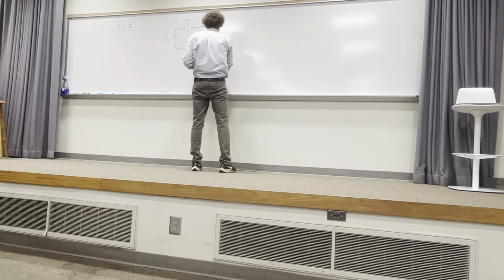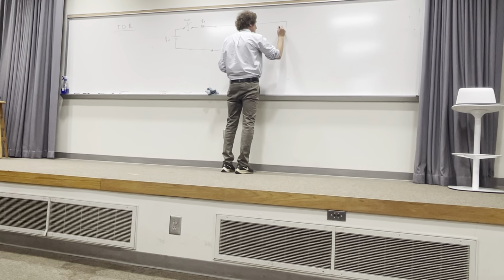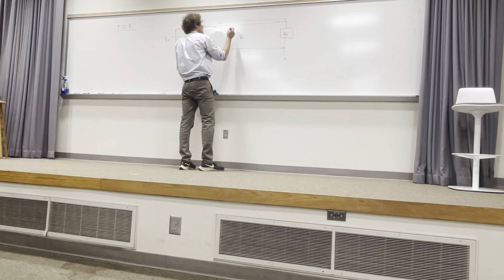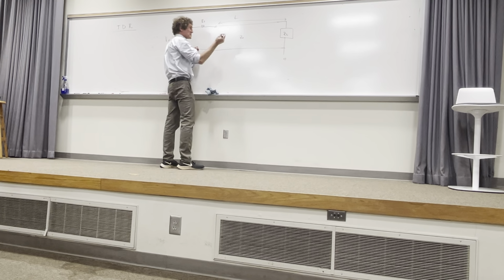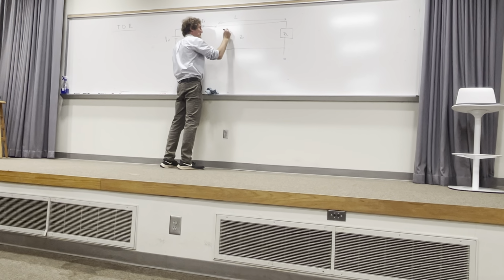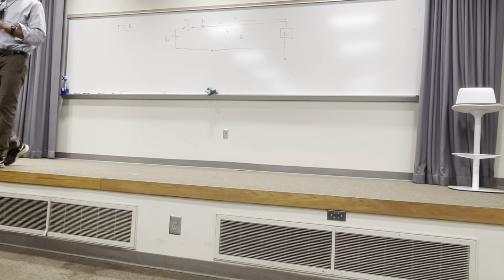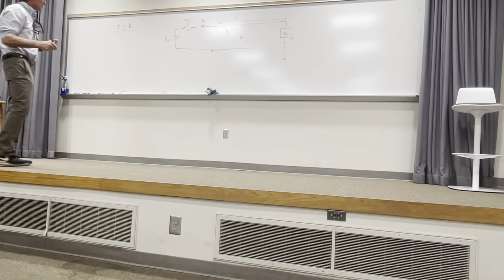So here, we're going to have a transmission line with a characteristic impedance of Z0. You're going to have a load over here, ZL, and you can call that 0. We're going to say the length of this line is L. That's the characteristic impedance. We're going to say the speed of light on this line, or phase velocity, is going to be the velocity of light. It doesn't have to be, but pretty much all lines are about the speed of light for transmission lines worth their salt.